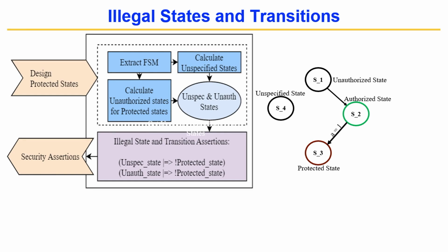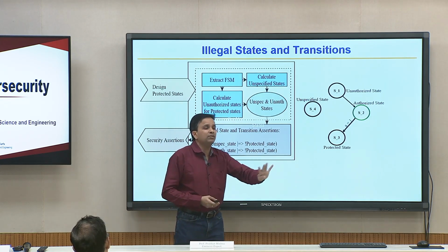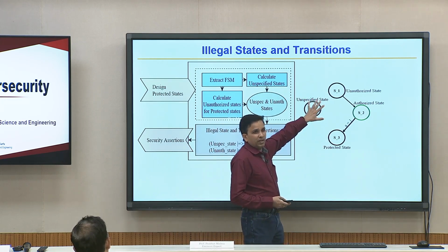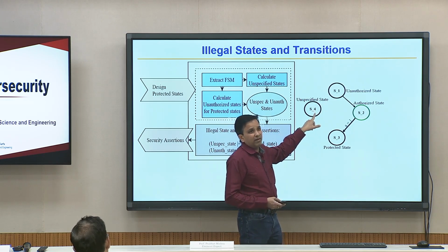In your mind you are thinking the finite state machine will have 3 states, but in reality if you synthesize using any synthesis tool, for example, Synopsys Design Compiler, whether it does one-hot encoding or binary encoding, it is going to create 4 states. You did not design it, you may not pay attention, you may not test, but that state will be created.